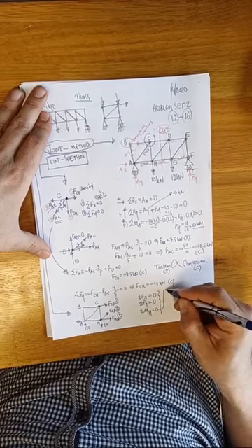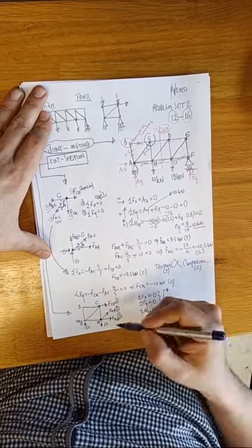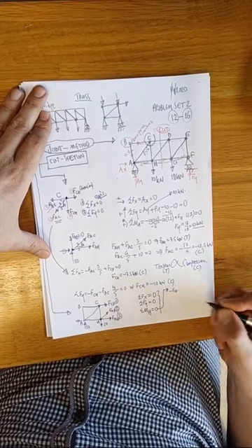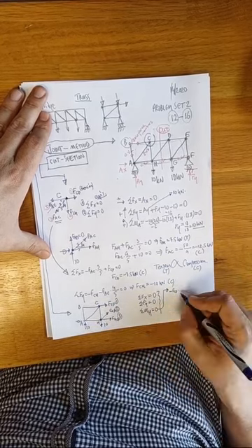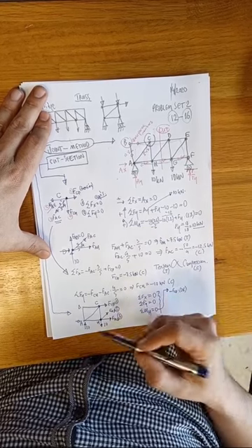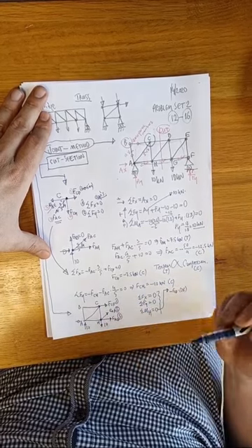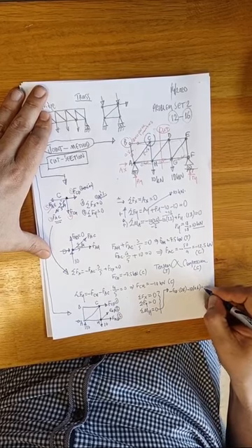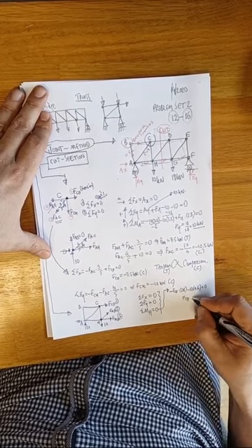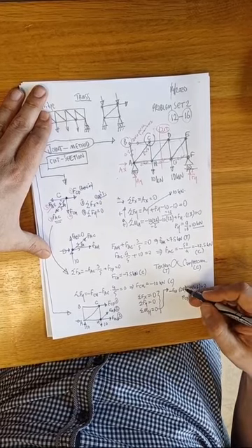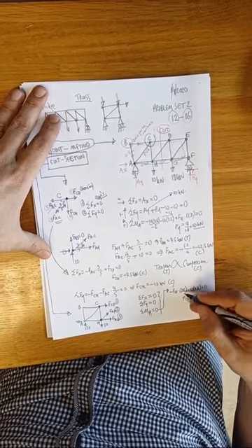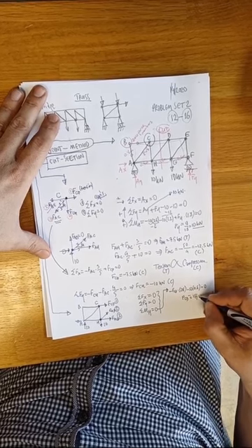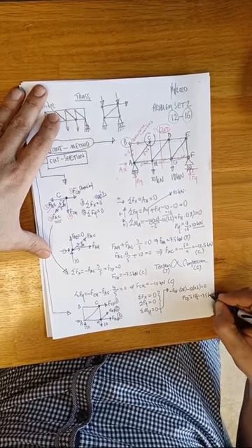For example, let's take this third equation directly. Minus FCD times, this is the length, which is 0.8. The other force is 10. 10 times 0.6 must be equal to 0. Gives you FCD is equal to what? 60 divided by 8, 30 divided by 4, 15 divided by 2, but minus 7.5 kilonewtons, which is what?